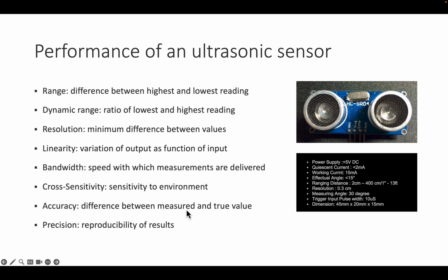What usually happens is you would buy a sensor like this, and then you would do experiments in the domain in which you want to use your sensor. Let's say you want to establish whether you can detect a little tricycle behind a parked car. Well, you do an experiment with devices like this, smaller and bigger, and then you can determine experimentally how small an obstacle can be for you to detect.